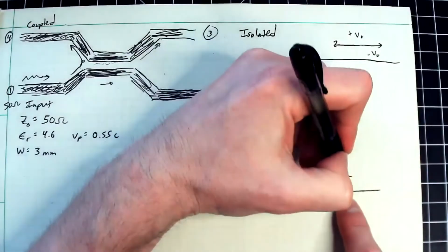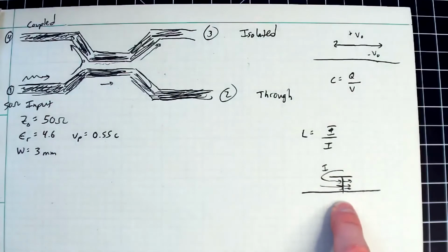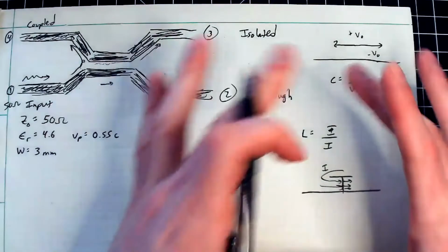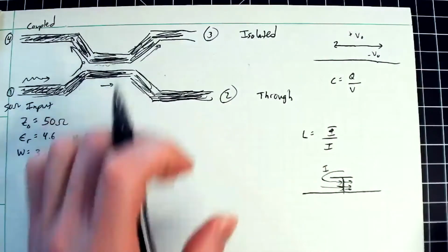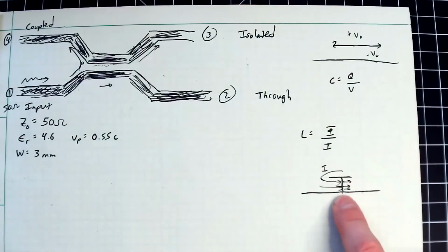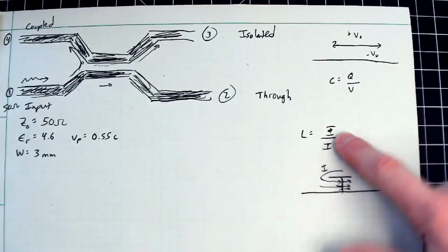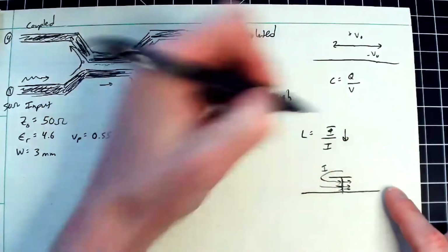You remember that I have to integrate the magnetic field across this little area here. So if I take that same current and spread it out, my intuition says the magnetic field intensity is going to go down, even though the current might stay the same. So that would imply my flux goes down, and so my inductance goes down.